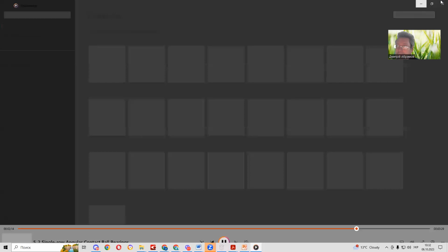And the tolerance field of the holes of the housing, from F to P. It can be IT grade 7 or 6 or 8.